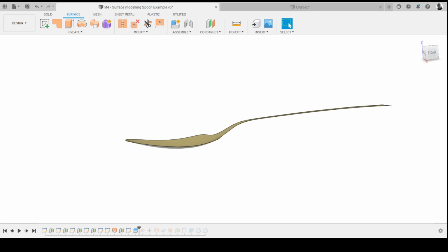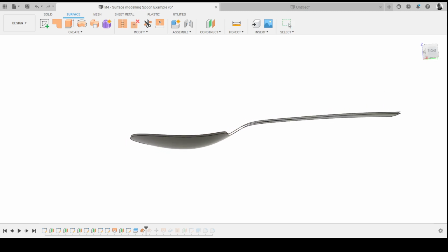Yeah, so that is under the create menu, offset, that one there. That will give you basically an offset there. I was following through your timeline in that, and what you do after that is a move. That's right, directly after that. You probably could do that as a move copy actually and save yourself a step, but I wanted, as I say, to show you the offset function. Then, to answer your question about the move copy, yeah, you're right. As I hover over this, it kind of moves around, doesn't it?